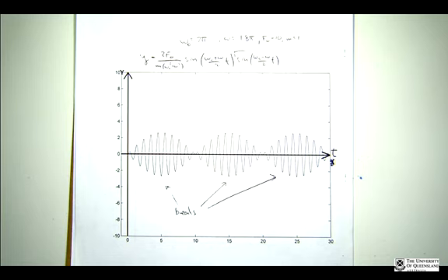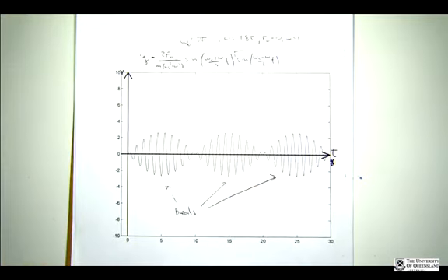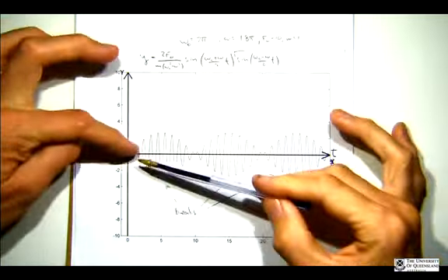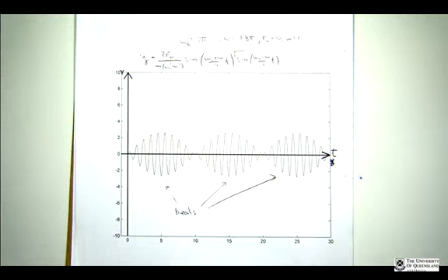Now we can see the frequency of these oscillations, describing how the amplitude of the oscillations, the sine of omega naught plus omega, is changing with respect to time. They're growing and contracting. This is what we call beats. When the driving frequency is very close to the natural frequency of the system, we're close to resonance, and beats arise.